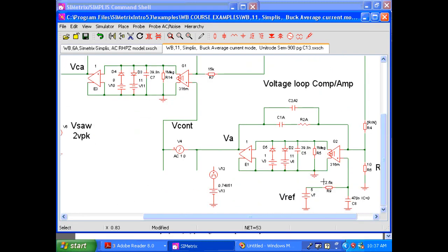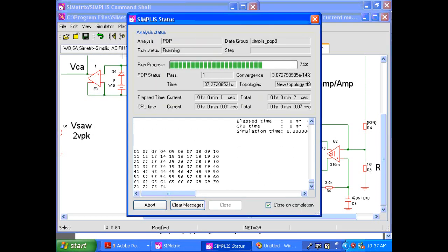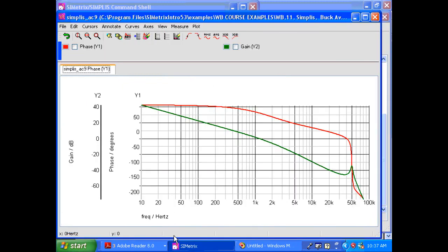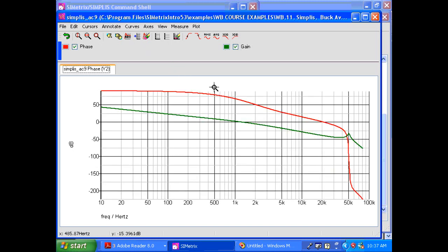One last point is to show you what the loop looks like again with too much feedback, where we have too much feedback. Place the Bode probe here. Simulate a run. And that's what the voltage loop would look like. Are we in trouble? No, not really. I'm going to raise the ESR though in a moment. Remember, the ESR is 1 micro right now. So at this point we actually have 65 dB. That's not bad. We're fine here because this never comes up to 0 at this, with these values.